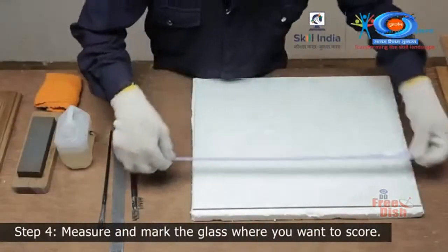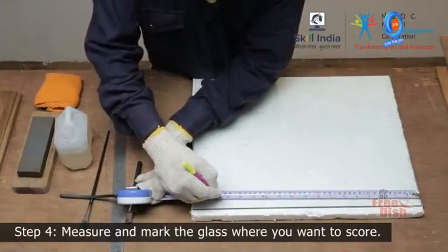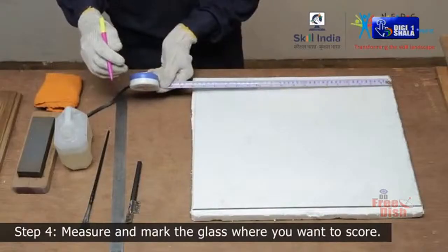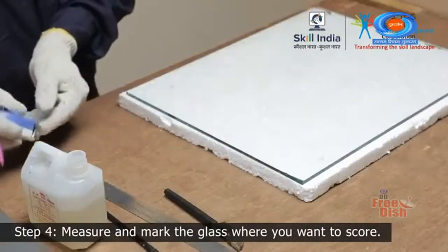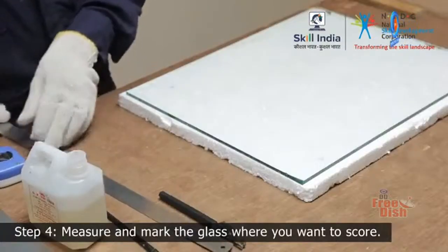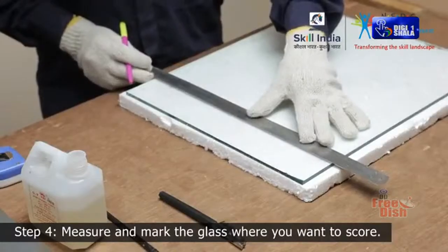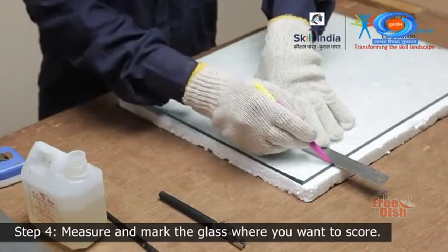Step 4. Measure and mark the glass where you want to score. Leave about 6 inches of glass on each side to grip and break. Use a marker and a straight edge to draw the cutting line. You can also mark on paper and place the glass on top of the paper.